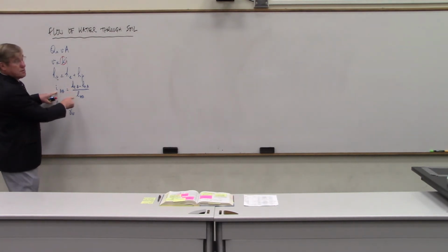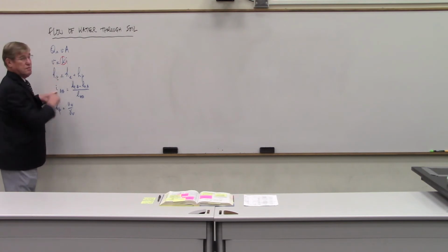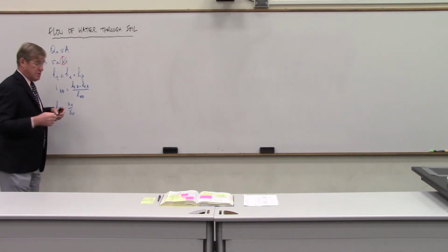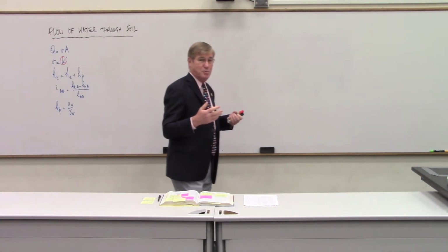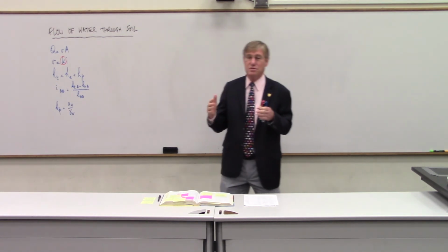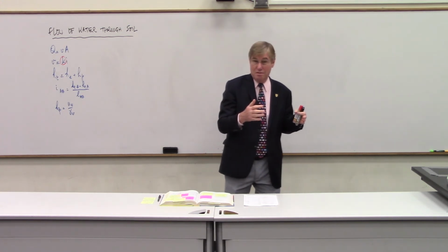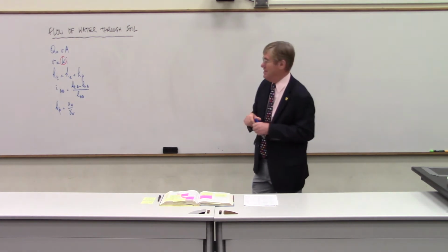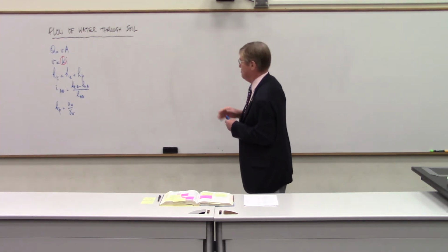Length divided by length. So the units of K will be the units of V, meters per second. But the water is definitely not going at very high speed in the soil. So we're going to be looking at numbers that are 10 to the minus 2 to 10 to the minus 10 meters per second. So it's going nowhere fast, but it is going. And you saw the Teton Dam, it is going, and it can do some significant damage.